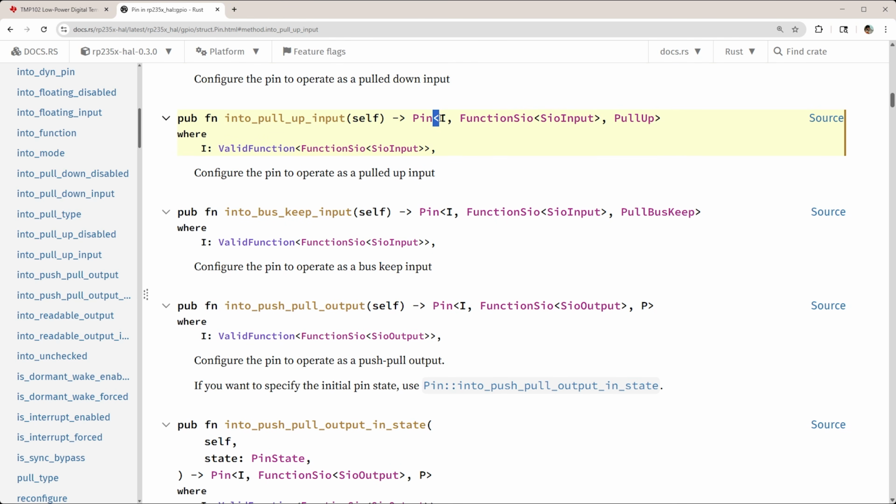These angle brackets here tell us that it's returning a generic of some type Pin. It's going to be set here with some function. In this case, it's going to be set as an input, and it is telling us to pull up that resistor internally. The I here is a pin ID. This maps to one of the usable GPIO numbers on the back end.